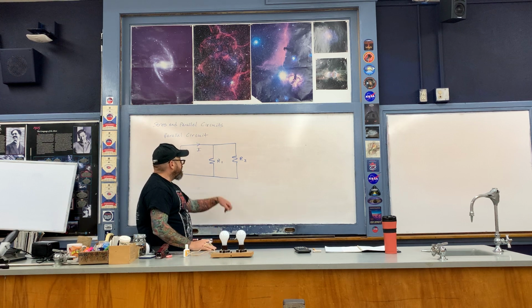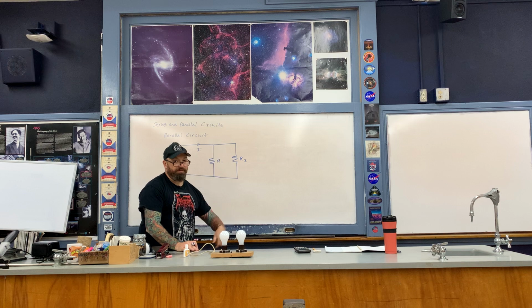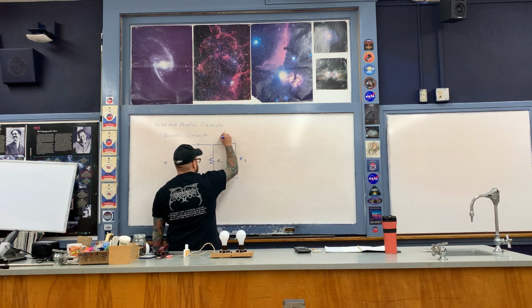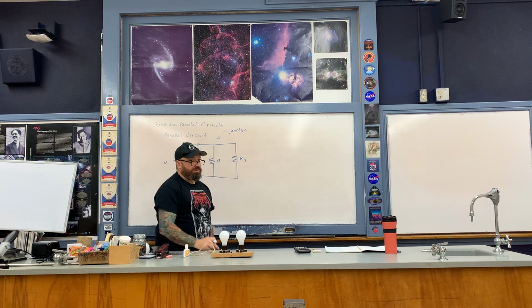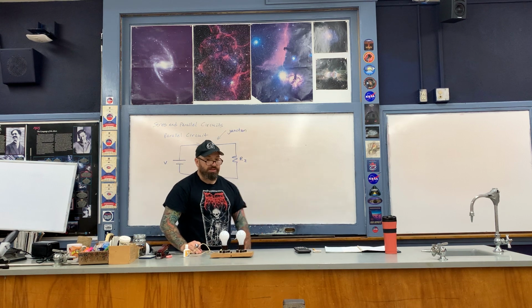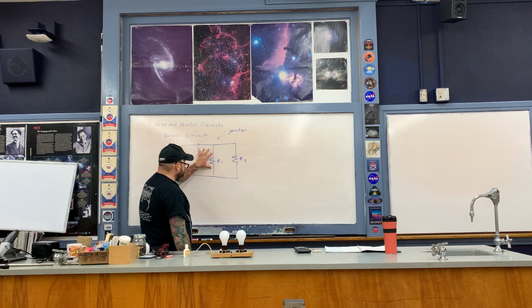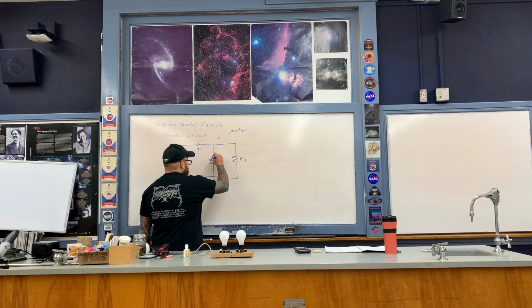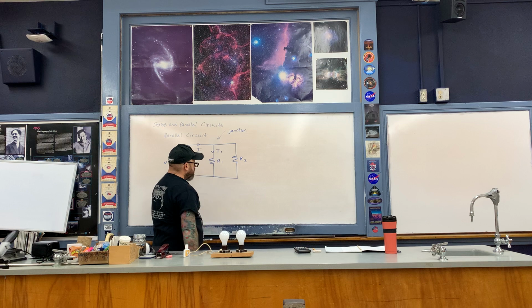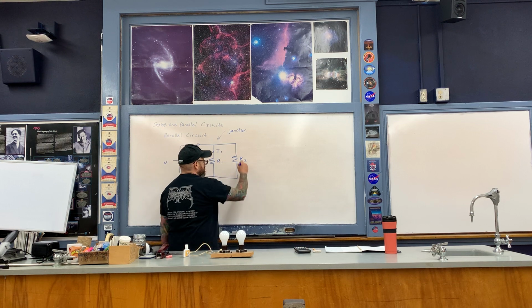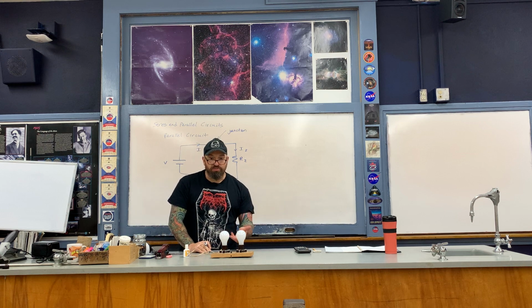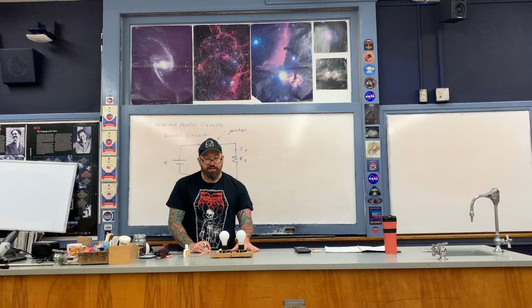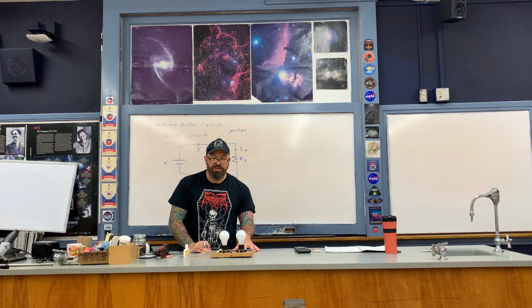And then notice that the conventional current here encounters what is referred to as a junction. When it encounters a junction, it splits into two parts. So for example, flowing through this branch, as we say, of the circuit, is going to be a current I1, and then flowing through this branch over here is going to be a current I2. The sum of the two, I1 plus I2, is equal to the original conventional current I. This is cleverly known as the junction rule.